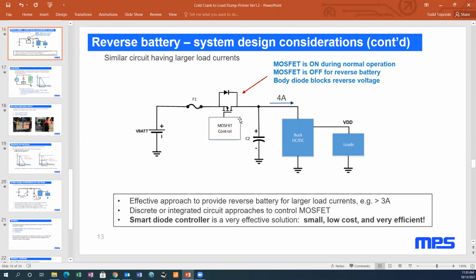A couple of ways to do that would be by using a charge pump in this control circuit, or some type of small boost converter that would always guarantee that the gate drive for this N channel is higher than the battery. There are also similar circuits where P channel FETs are used, and in those schemes, you don't need to have the higher gate voltage. You're able to pull the gate voltage low, or close to ground, to enable the P channel FET.